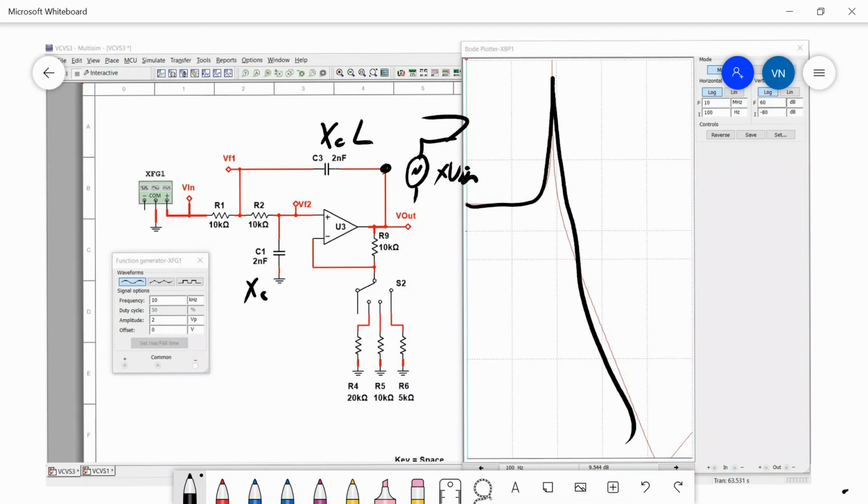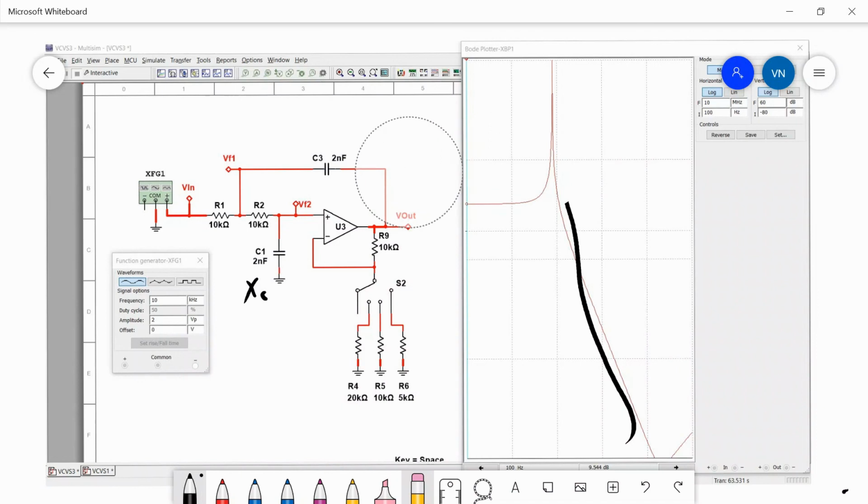Now you could also use Laplace transforms and work on this problem in the S domain. And you're going to learn how to do that in your advanced calculus course. But the reality is that in order to find or design these filter circuits, what ends up happening is that there's a cookbook of known good circuits that you can start with, and you would put them into a simulation package like Multisim, and you would tweak its values.